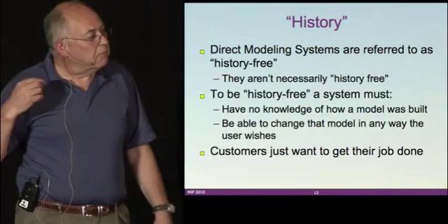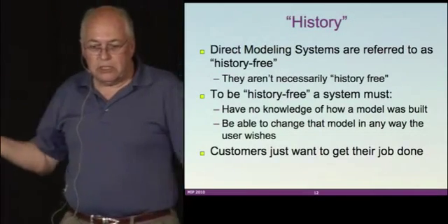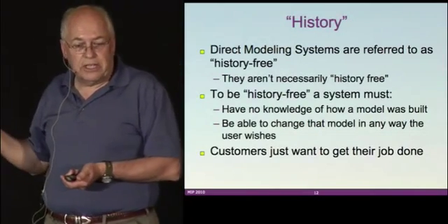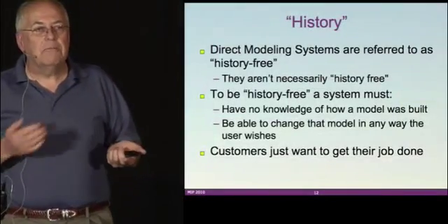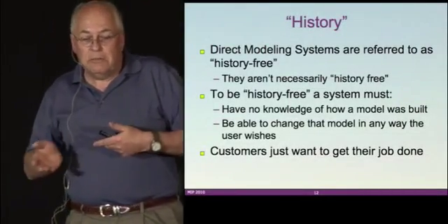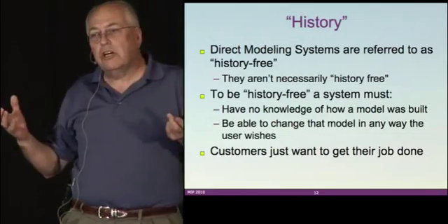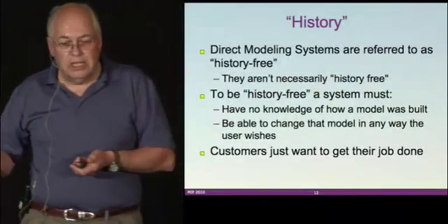And often direct modeling systems, and we all know some of them, are referred to as history-free, but they're not necessarily history-free. To be history-free, the software must not know how the model was built. It's nice if it did, but it doesn't have to. You give it a chunk of geometry and you can work with it. And you'll be able to change the model in any way the user wants.